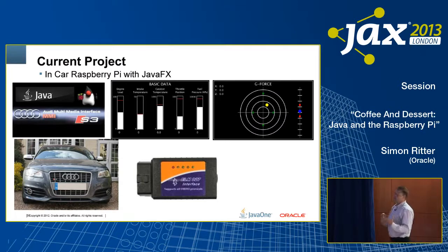And so you can find out what the different values of things like where the throttle is. You can find out things like what the engine temperature is and what the engine load is. And if you want to be really daring, you can actually then also communicate through what's called the CAN bus. The CAN bus is the sort of more proprietary technology that people use in cars nowadays because the wiring is so complicated. So if you can decode the CAN bus signals, you can actually find out all sorts of weird things like what angle the steering wheel's at, or where the electric window is in terms of what percentage it is up or down. And then you can start writing things as well as reading things.